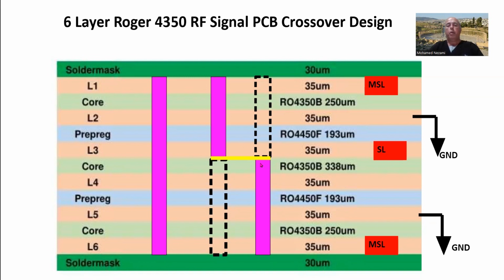So I'm going to go from top to the strip line using the same via here, except do a drill back. That's the technique that you specify, and the PCB house you interact with knows which ones are programmed to be drilled. You drill this so that you get rid of the copper that is here. The reason we do this is because my RF signal comes in on top, goes down to here, and then goes to the strip line in here, and then goes down to the bottom or comes back up.